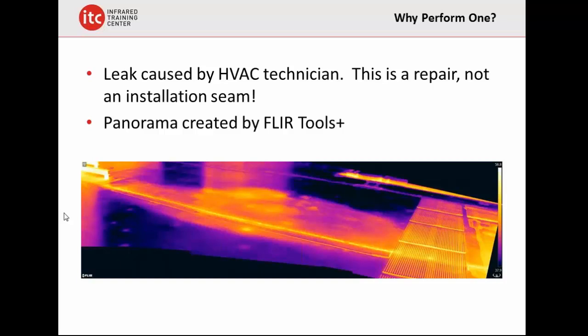Now this roof is constructed, this is black EPDM, there's a layer of polyisocyanurate insulation, fiberboard, then another layer of polyiso, and then it's right on the roof deck. And the water is in the fiberboard. And so we've left it like this. They offered to come back and replace the insulation and the fiberboard, and I politely told them, please don't, because now we have something really cool to look at.